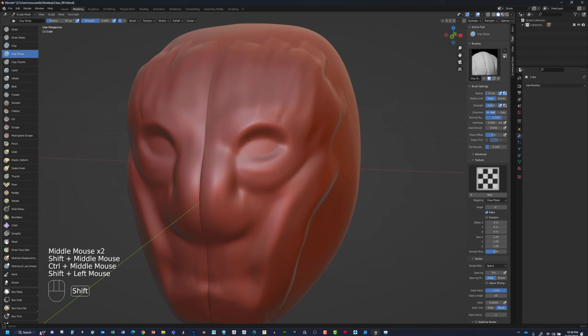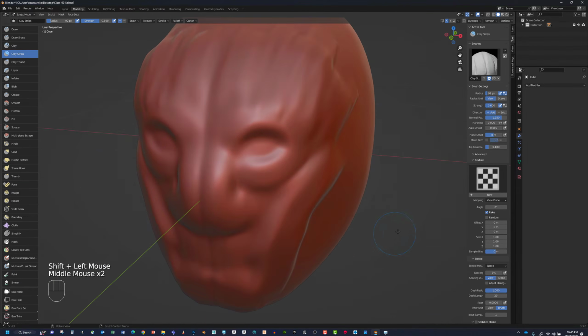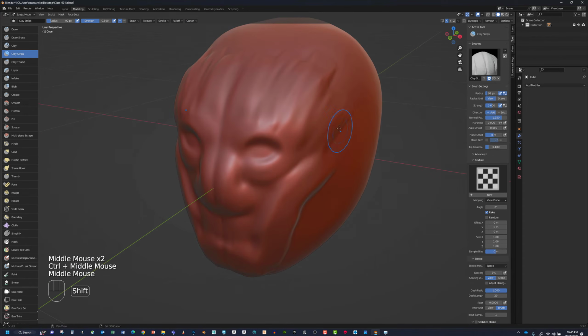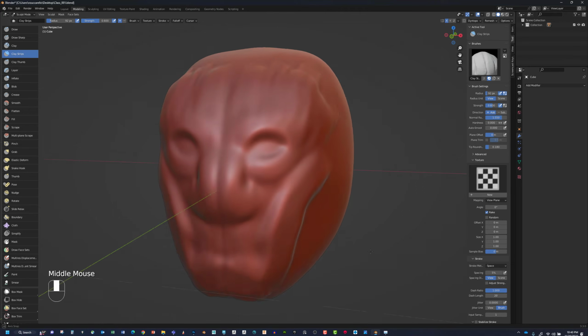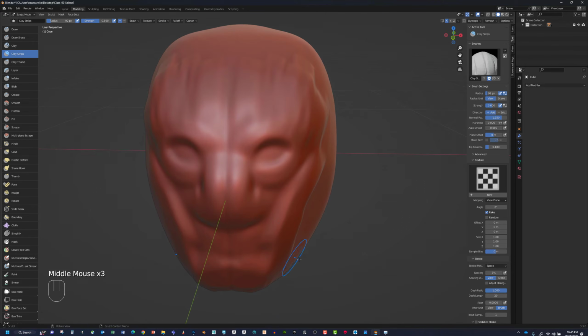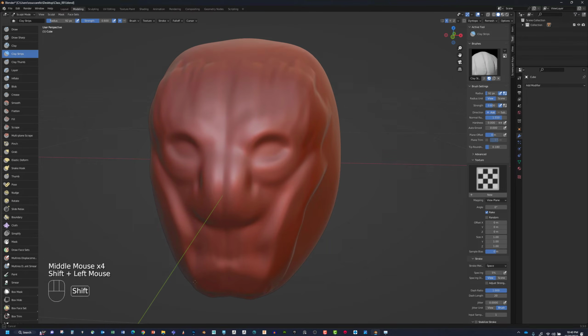So it's pretty dense. If I start to smooth this thing out, let's turn on the symmetry for this again and just smooth out the results and see. Now we can smooth across this thing pretty good. Okay, and so yeah, I'll keep it at that resolution as I'm working. But if you're using this topology at the very beginning, I wouldn't suggest having very much density to this. I do have quite a bit, but I was trying to preserve maybe some details that I've already sculpted.